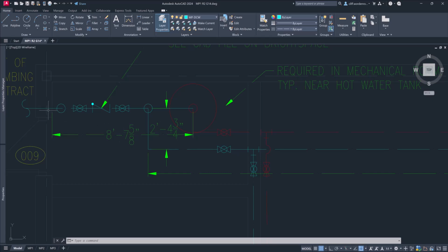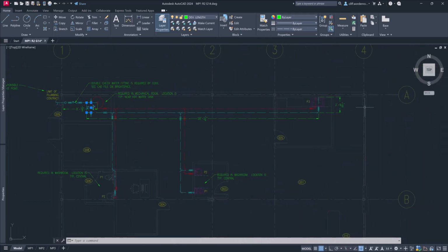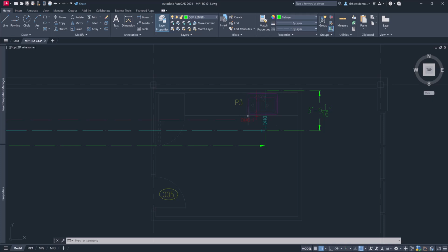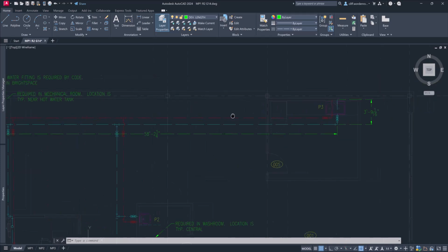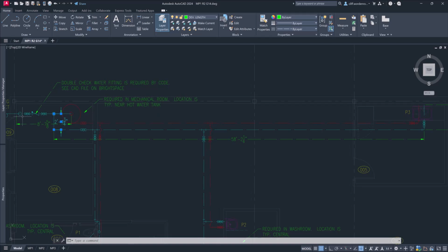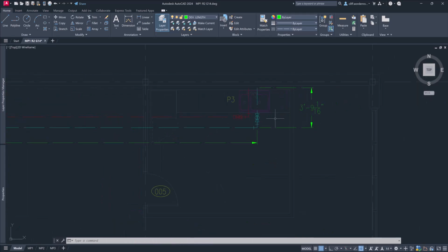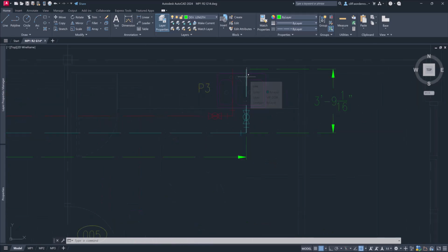So anyways, I start at the service entrance, from the wall. And then I measure the distance basically along a stretch of pipe. So here I've taken it from the hot water tank. I could have just as easily gone here and around. This dimension here is this length here, okay? And then what I've said is this fixture here, which is a sink, is probably my furthest distance away, right? So when I say measure along the pipeline, what I mean is start here, measure, and go all the way along, right? And then the last bit is measuring to where the pipe connection is.